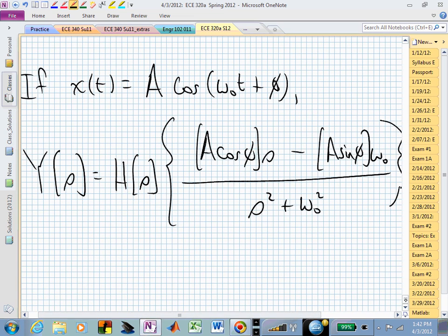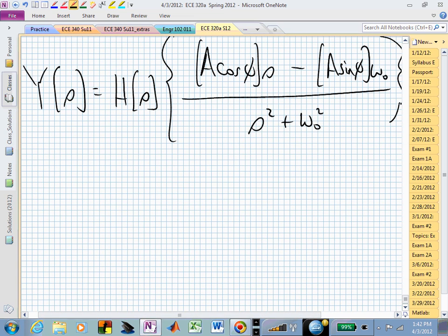In order for this sinusoidal steady state to even make sense, we need our system to be stable. If our system was not stable and we started shaking it, what's going to happen? You'd start smelling something burning, or it would blow up, right? If you had an unstable system and you excite it, it's going to go unstable. So let's assume that we have a stable system or transfer function. If we have a stable system, then if I shake it, the output will be a stable response, and it will just have an adjusted amplitude and a changed phase. That's the assumption that we're going to make.